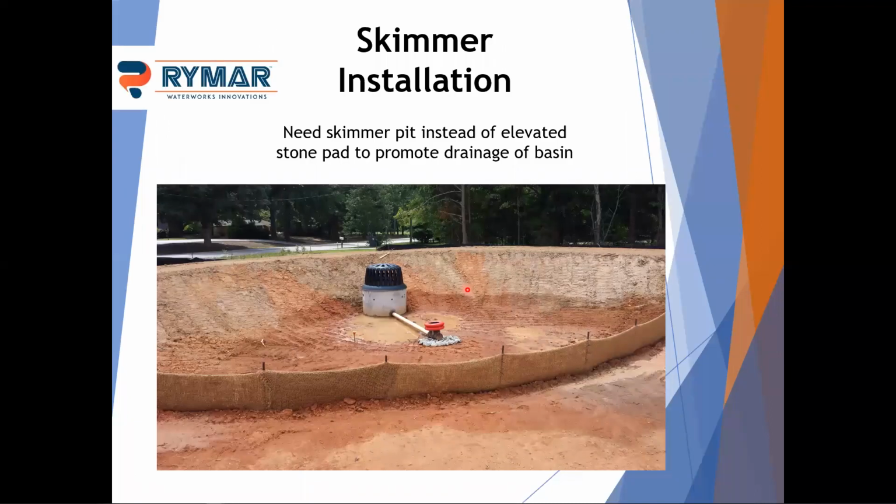So just a couple of things. I think skimmers are kind of new to most people on here today, so here are some things to be aware of if you haven't seen them installed. This is a pretty decent installation. It's brand new. The baffles are in. It's got a little pad for the skimmer to sit on, but you'll notice it's holding water here. Because they set the pad on top of the graded surface, the skimmer's not going to kick in until you've got 6 or 8 inches of water in the pond.